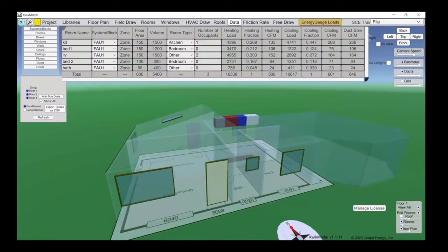And then when you're doing this early on, the other thing you're going to have to do, I have the advantage of literally having done thousands and thousands of load calculations. So I know what's important. I know what's not important. Until you have several hundred load calculations under your belt, if you're not sure about something, like people, run the loads, go back, change that one variable, run the loads again, and see how big of a difference it makes. You're going to have to do that over and over again until you have a good fundamental understanding of what's important and what's not.